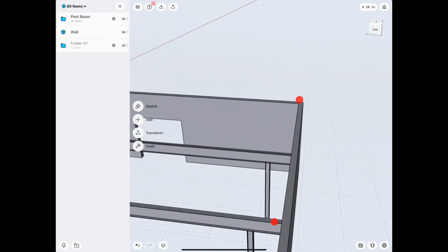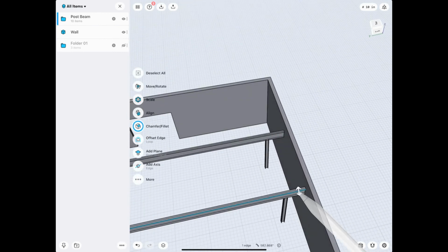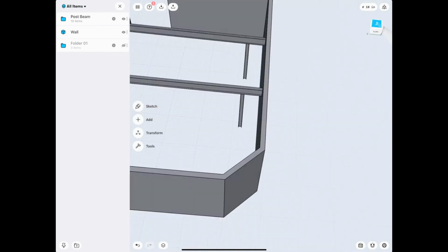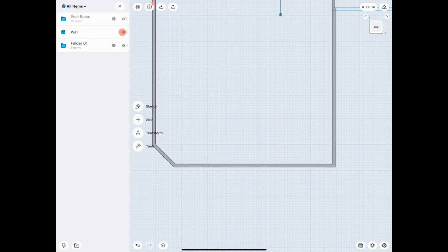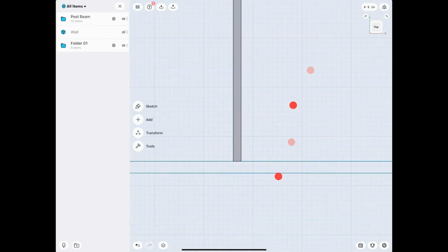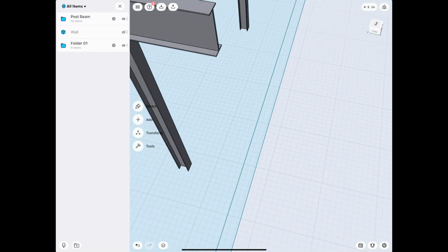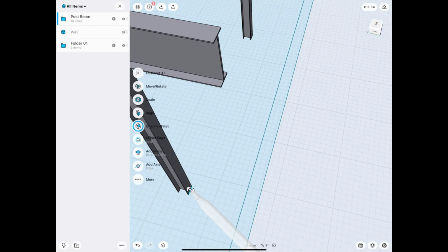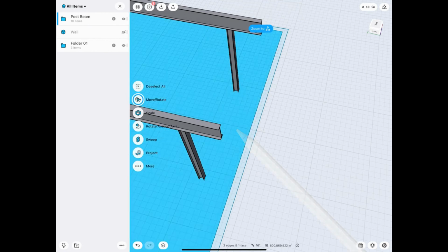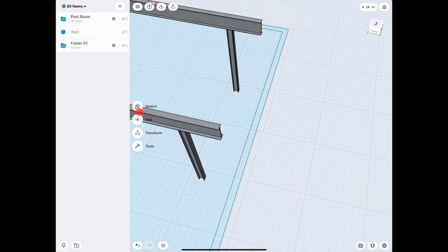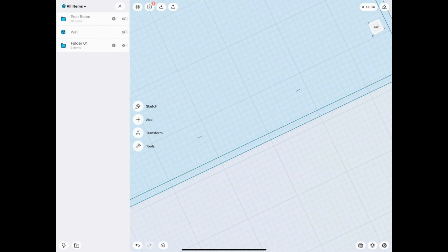Very nice. So we have a small post actually down here where this sits on. So let's go to this view, turn all this off, turn this back on there. Okay, now I want to know where, for example, is this stuff here. So this edge and this edge I will project onto this sketch. You see? Now I copied in the two lines. Super nice and useful.